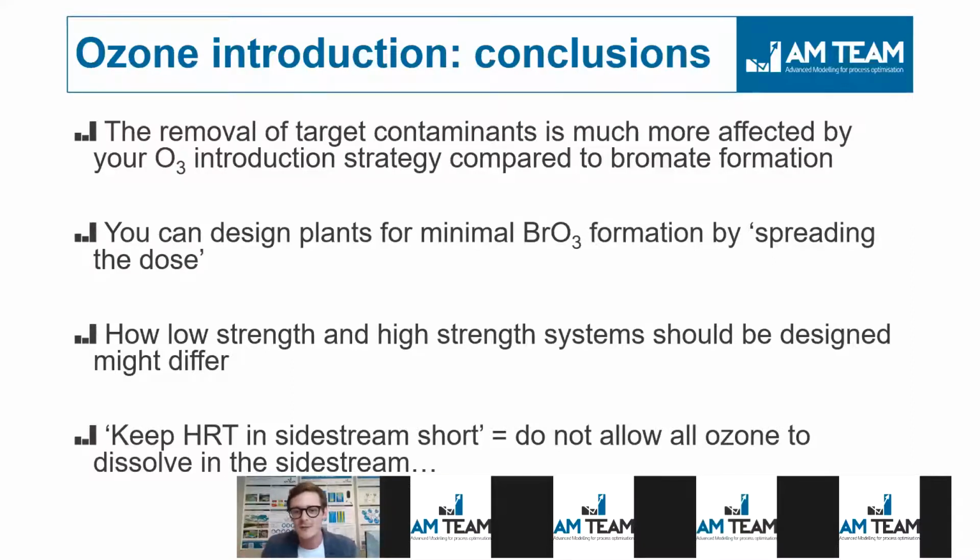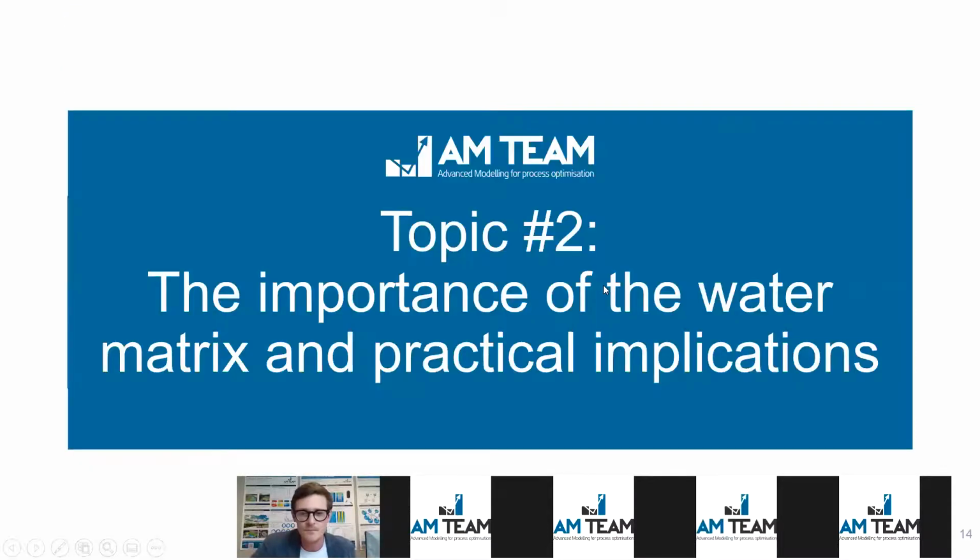Well, actually, you are saying do not allow all ozone to dissolve in the side stream. Because if that would happen, you go very, very similar to this first column Roberta showed, which is the more drastic case of a very, very fast transfer of your ozone in the water. So it has to do with the amount of uptake of your water locally, and also the amount of local transfer efficiency you have. This will, in the end, determine your final ozone residual, and your final ozone residual then leads to your local bromate.